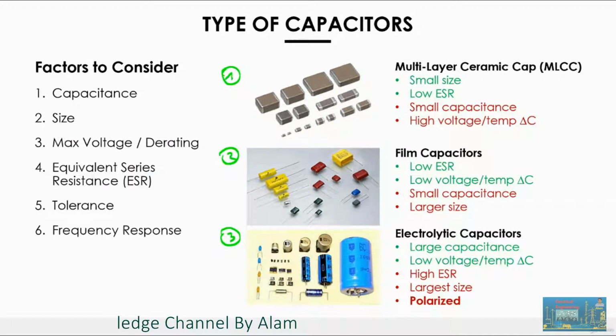There are many types of capacitors available on the market. If you just Google capacitor on Wikipedia, you will find materials for hours. I just want to briefly discuss three main families and the main characteristics. The first is the multi-layer ceramic capacitor, also called MLCC. These are a very widely used type of capacitors, probably the most used type. Their main advantage is the small size. If you look at the smallest size of MLCC available, this could be really tiny. Only a machine can really solder them well. The smallest size could be like 1/4 millimeter by 1/8 millimeter, so really tiny.